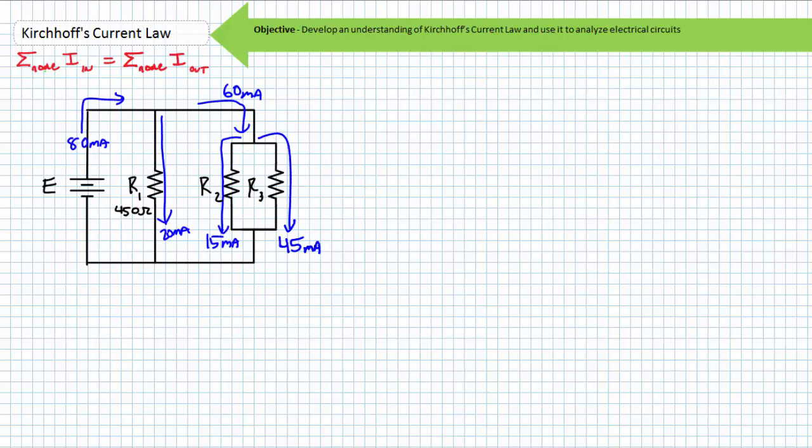The toughest part of this whole problem for some people is not electrical in nature, but rather the physical arrangement of these three resistors. They are all in parallel with one another. I simply cannot stress the importance of voluminous practice and repetitive exposure if this is not readily evident up front. These resistors are in parallel with one another because they are all two-terminal components with one of their two terminals hooked to the same point. This amorphous blob I'm calling node A. Yes, within node A, there is a subdivision, but all three paths originate at this single point.